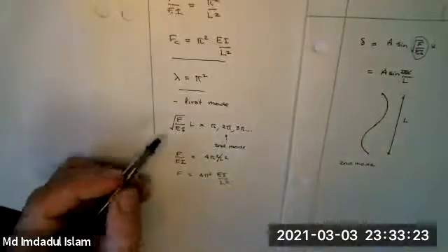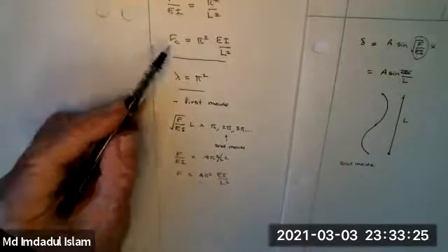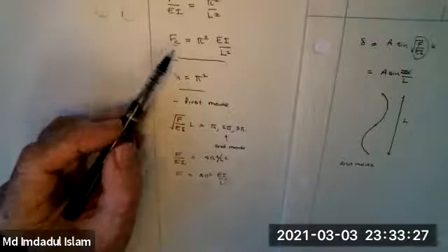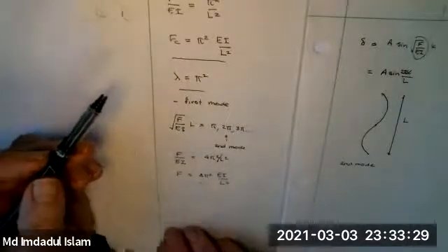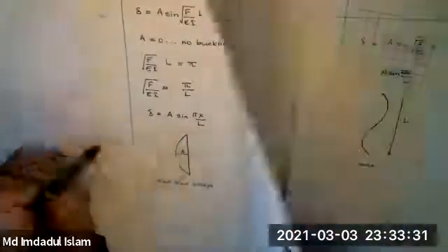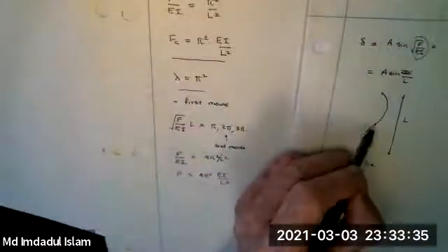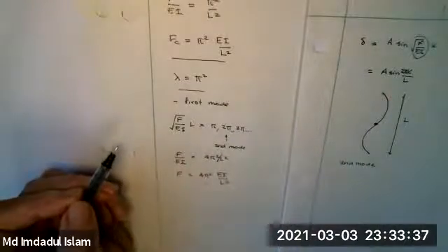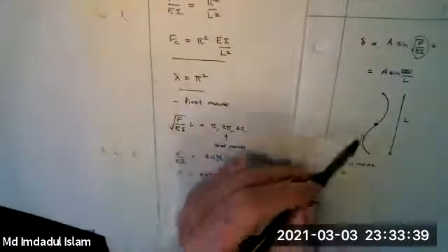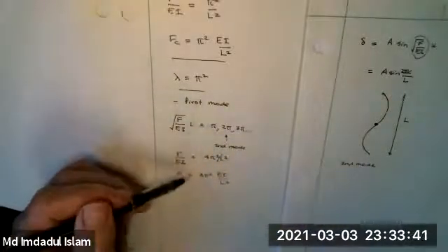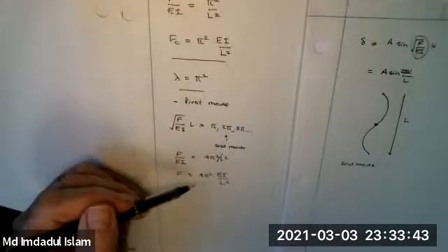While, as I pointed out, if you're just loading this simply supported beam, you're going to hit this load first, so it's going to buckle with that first mode shape. Okay. And you won't see this. You can come in and hold the middle and force it into the second mode, and that'll get you a higher buckling load, so that'll inhibit the buckling.